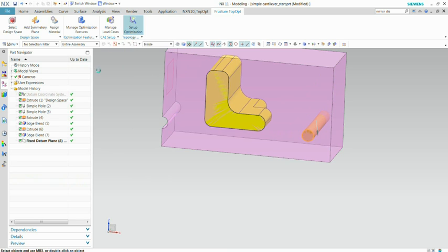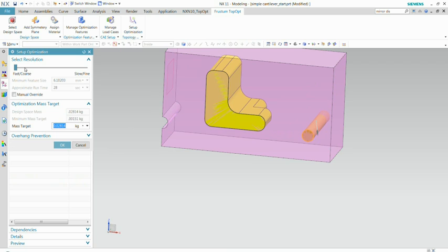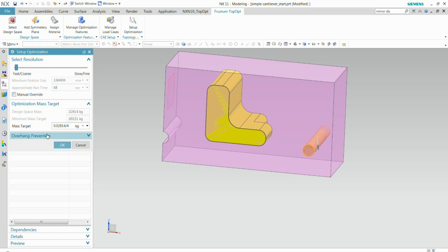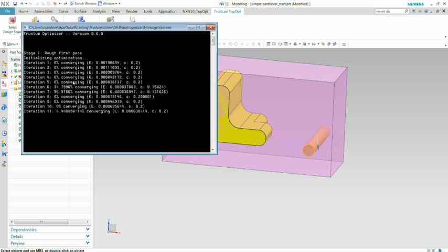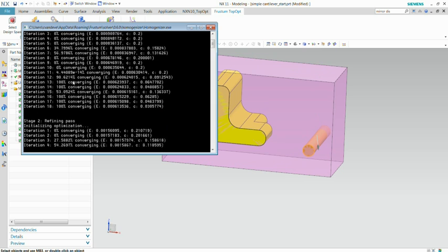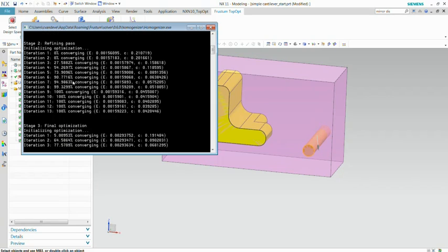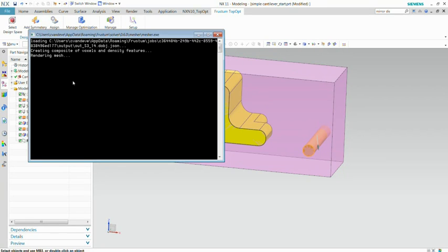Finally, I'm going to define the setup of my simulation. I didn't apply a maximum displacement or something. I'm just saying, well, try to have an optimum shape when the weight is divided by 4. And we can define the precision of our results. So the more fine we make, the slower the simulation will be, but also the more precise the result will be at the end. I'm going to show that in a minute.